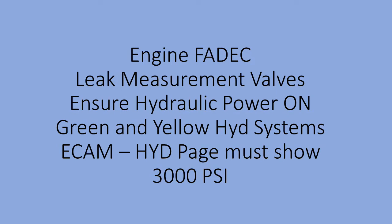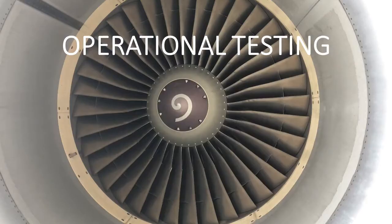Remember, that's engine 1 and engine 2's hydraulic systems. Then check on the HYD page that you do have the right pressure, because across the board, unless we're talking about the A350, we're just talking about Airbuses, and Boeing is pretty much the same as far as the pressures. The operating pressure is 3,000 psi.